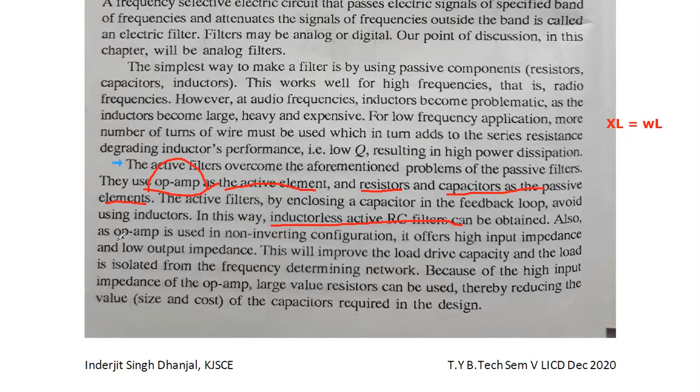So op-amps, you know that if they are used in the non-inverting configuration, they offer high input impedance and low output impedance. What this will do is improve the load driving capacity, and the load is isolated from the frequency determining network. So that's why we use this.